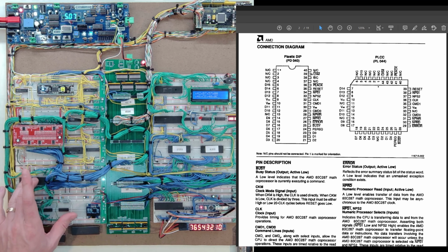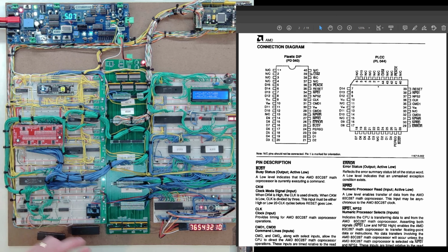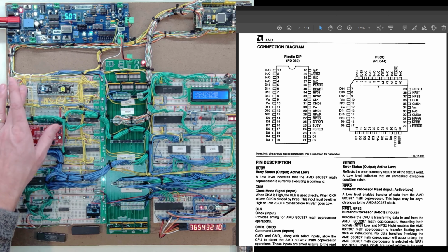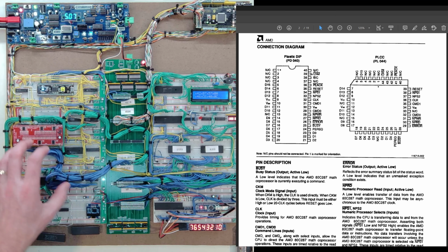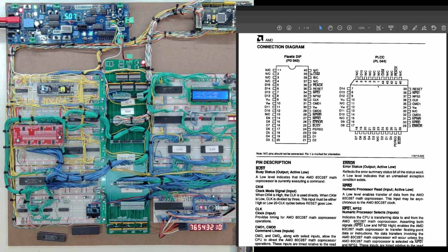I have had a previous recommendation, this was on my video card, but I think the recommendation could apply here. Should I get some type of clock distribution IC in here that helps me take a clock and better distribute it to multiple devices, instead of loading up this one pin with all of the devices that are using the clock? That might be something I should consider. If anybody has further input on that, let me know, but maybe in a future update I could consider putting in one of those types of chips that helps distribute clock signals to lots of devices.